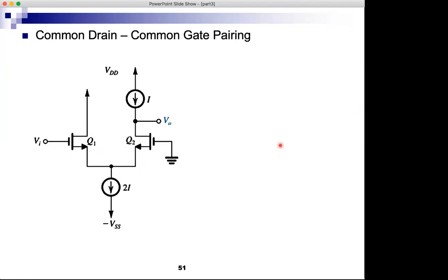Well, the input resistance is very high, it's infinite actually, and that's much, much higher than the input resistance of just common gate, but it's not better than common source. So we're back to the common source level of input resistance, which was infinite and is infinite here.